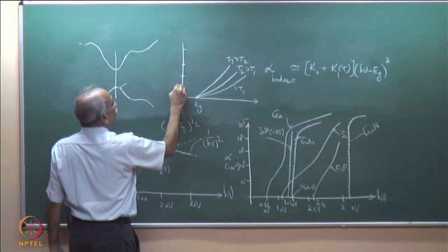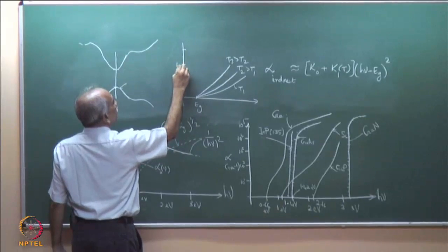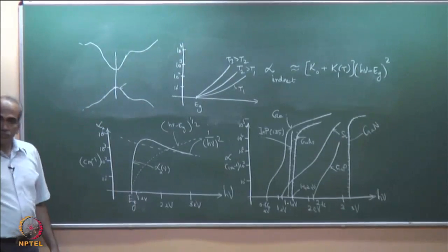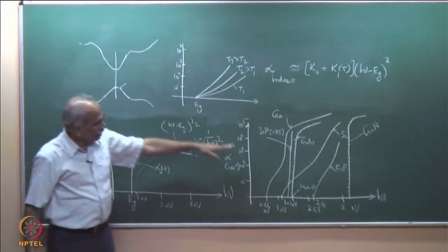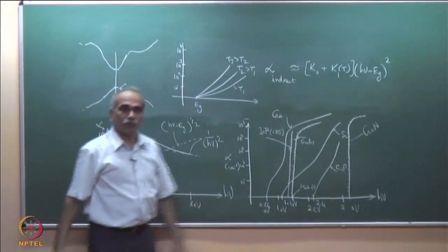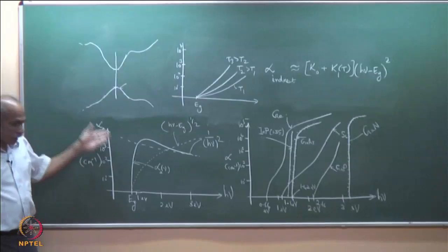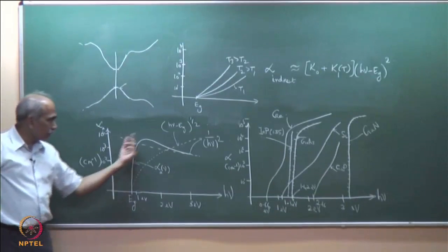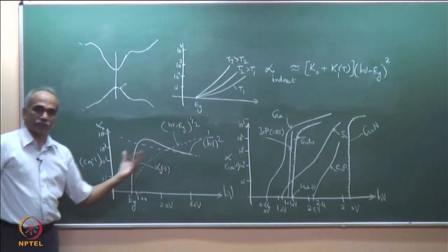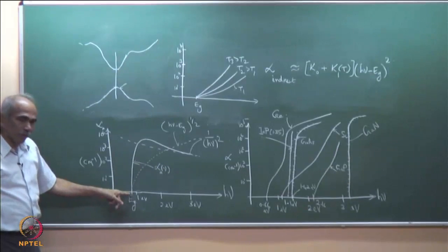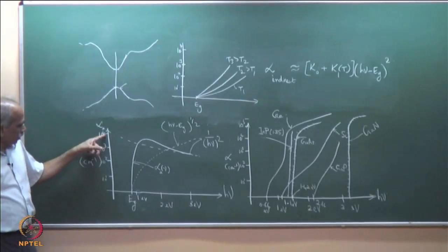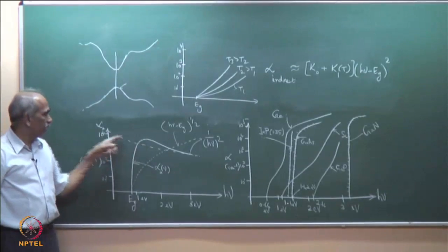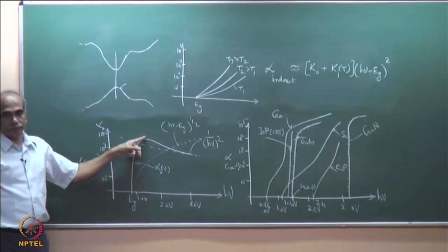So, 10 power 1, 10 power 2, 10 power 3, 10 power 4. So, they are a little smaller. You can see these have already reached 10 power 4. The direct gap has come to 10 power 4. This particular graph is approximately calculated for gallium arsenide. So, it should have been 1.42 eV, because if you use the parameters of gallium arsenide, then approximately 10 power 4 is the peak.